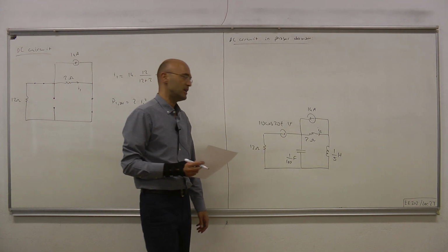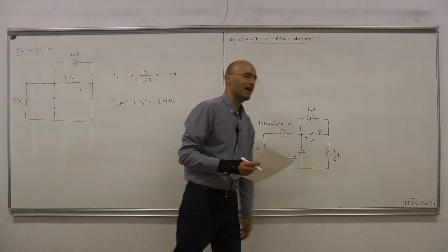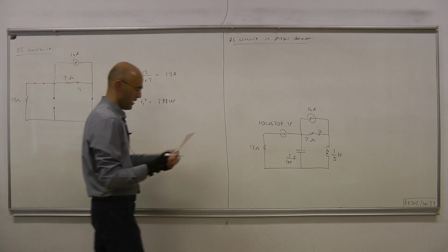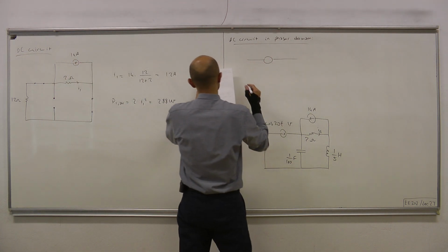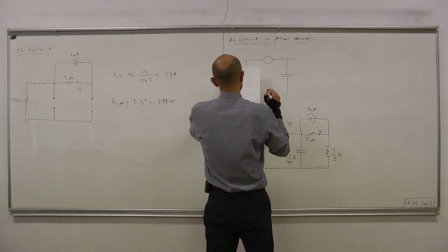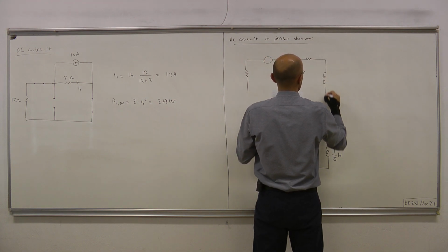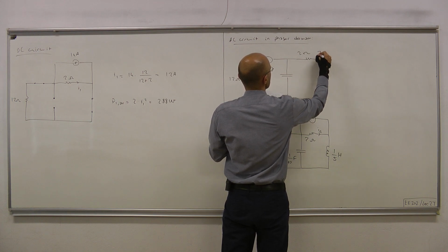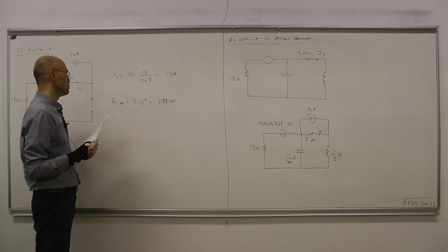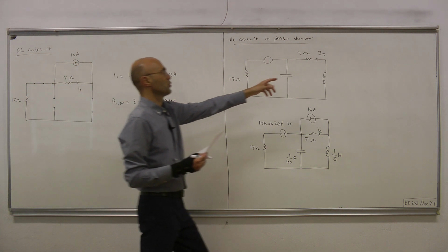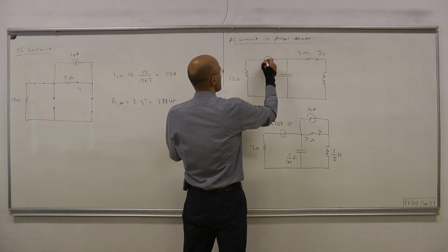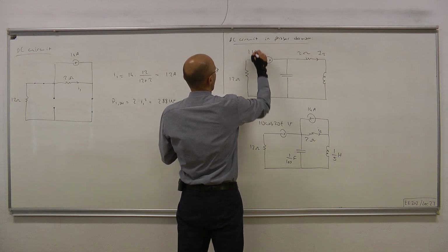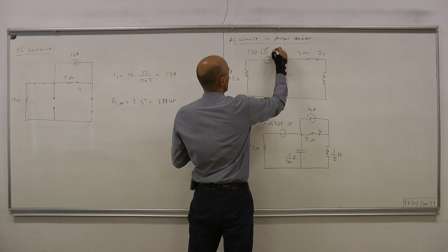the components by their impedances, which is 1 over j omega c for the capacitor and j omega l for the inductor. As for the resistors, we directly carry the resistances to phasor domain. And once that's done, this is our simple circuit. 12 ohm, 2 ohm, and now we're interested in I2, the component due to the AC source. In phasor domain, its phasor is denoted by capital I2. The source is 110 magnitude and phase 0 volts.